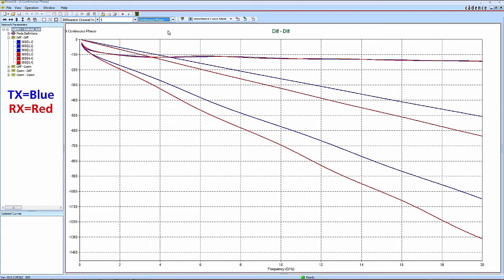longer. But before we go to the next step of local simulation for the cut design, let's consider what these results tell us already. The phase behaviors tell us the reflection occurs dominantly, if not entirely, at the board side transition over the entire bandwidth. Since the board side reflection phase starts at about -90 degrees and decreases slowly with frequency, we know this transition is highly capacitive and localized to the board side transition.